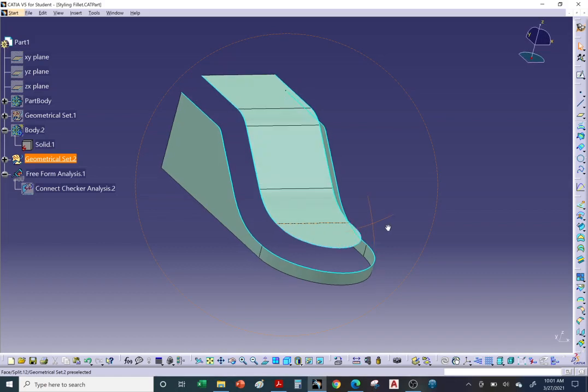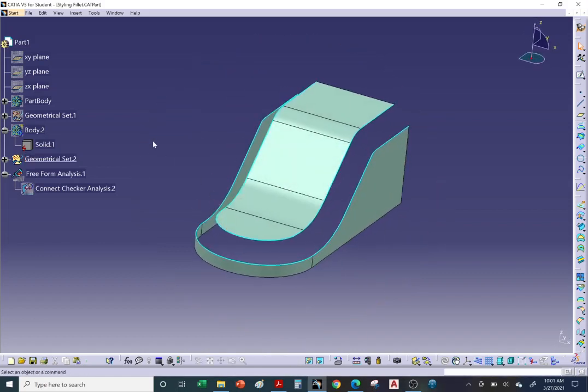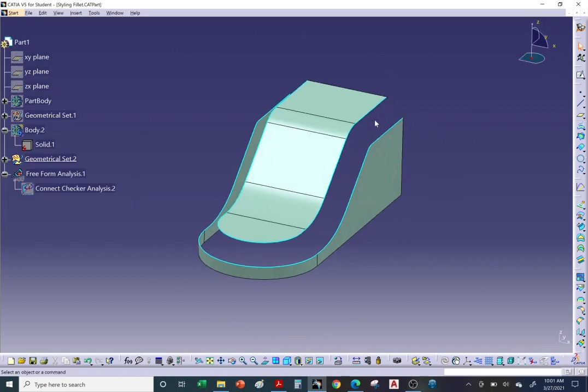One of the biggest headaches in modeling, whether it's CATIA or any other surfacing or even solid modeling, it can be Unigraphics, SolidWorks, Alias, any other software. One of the biggest headaches are the fillets. When you do a straight fillet, if it's a simple straight fillet like you see here, it's not an issue. But when it's traveling and turning and sometimes it doesn't know which direction to go, it's going to give you error messages, and it also eats up a lot of memory. So it's generating a shape as it's traveling along, and it's eating up a lot of memory as it's generating and going around the curves.